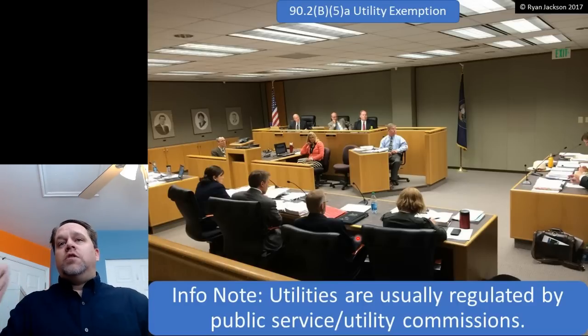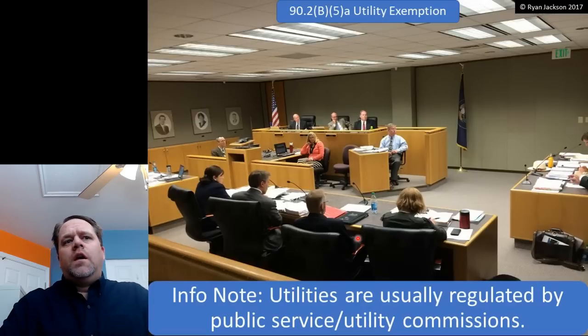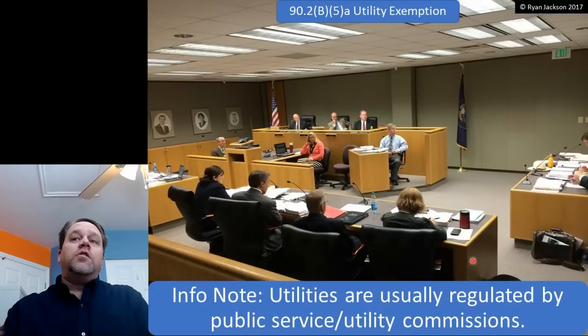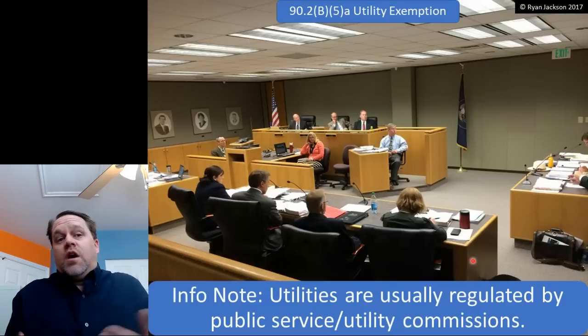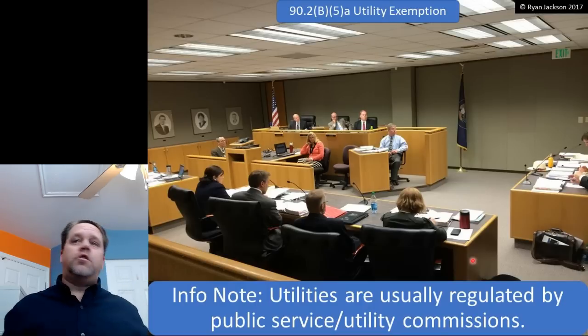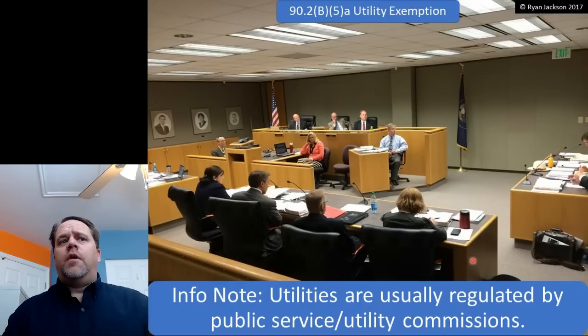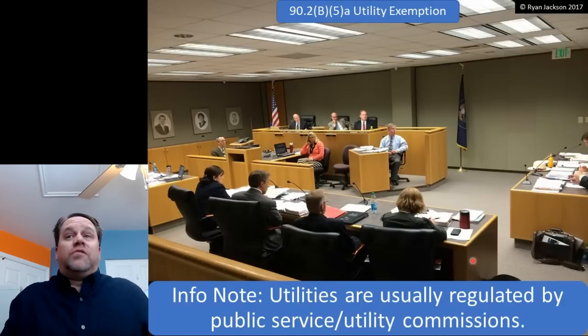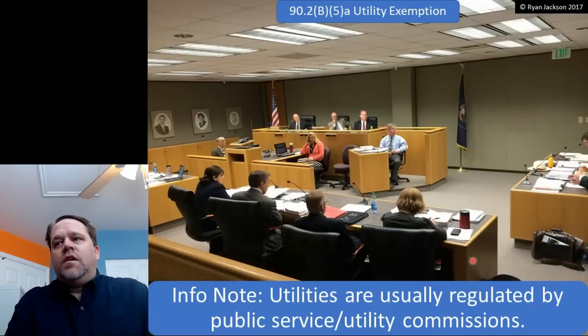We don't cover utility installations that are transmission, distribution, etc. But you're only a utility if you're regulated by a public service commission or a utility commission. Who are you selling electricity to? Well, nobody. We're generating it and we're using it ourselves. Okay, well then you're not a utility. You're not regulated by a public service or a utility commission. It doesn't matter that you have 25,000 volts. That means nothing. You're still regulated by the code if you're not a utility.